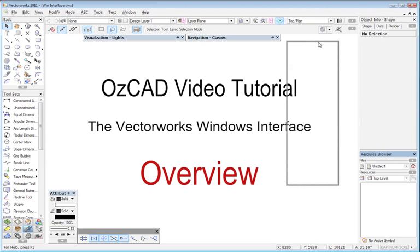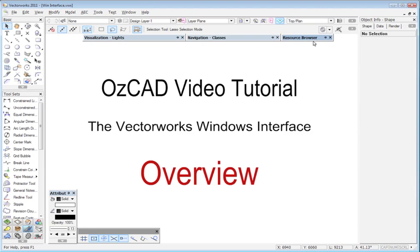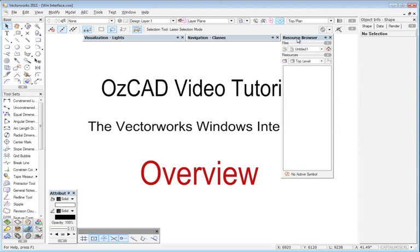And I can take it out just by clicking it and putting it back to where I might want it to be. Now with these palettes here, we have them set so that if you hover over the title, they will automatically drop down. You'll see if I hover over classes, it drops down, and so on. That automatic dropping down is controlled by this little pin icon here, and if I click that, it's called auto hide, then the palette will just stay down permanently.